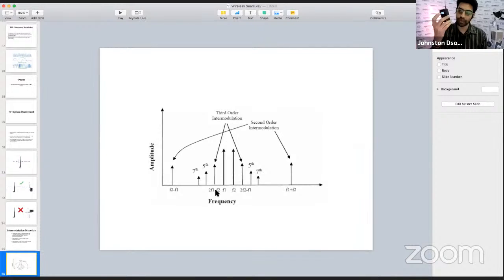So what these manufacturers do is they'll take your entire frequency bands and start making groups, and the groups are made so that there is no intermodulation frequency. So for example, bank 1 will have about 16 frequencies, and each of the 16 frequencies are far apart from each other. So between those 16 frequencies, there won't be any intermodulation.